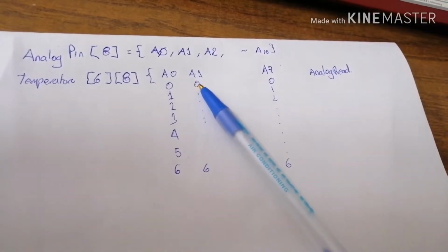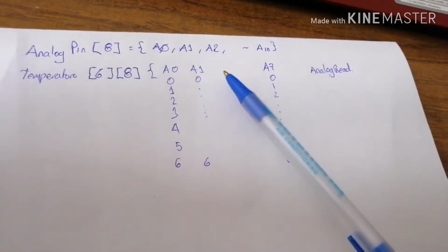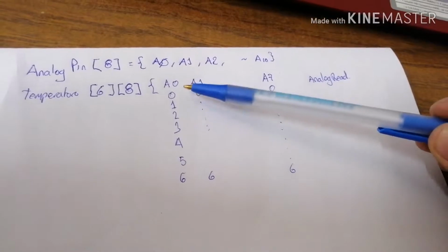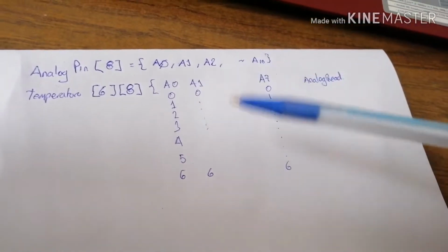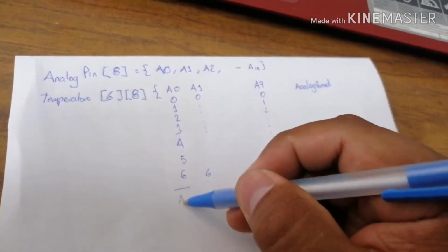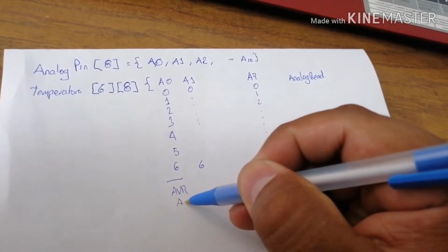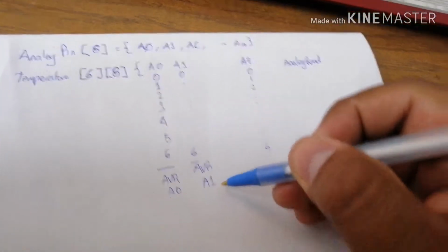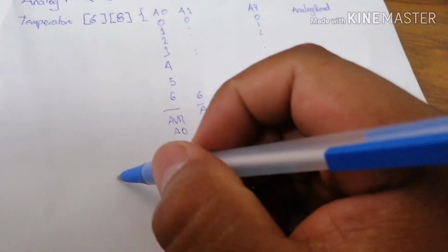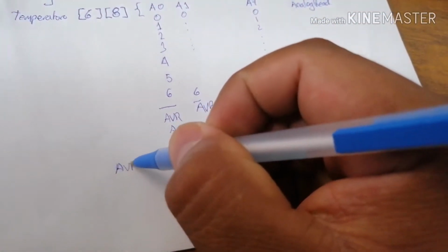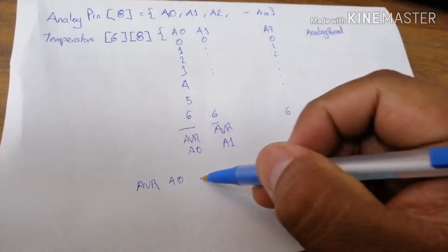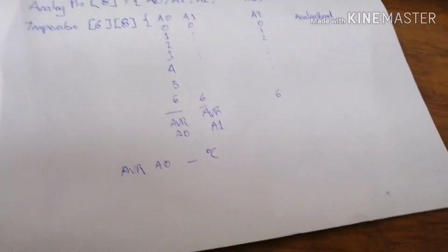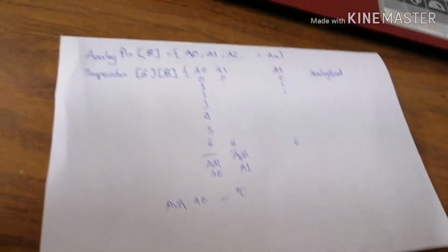I do not take all measurements in a row, because I want to have some time between them, and in the end I average this and average this and so on. This number is converted into a Celsius temperature using an equation. The equation is in the code, so you don't need to do as much work, I have already done it.